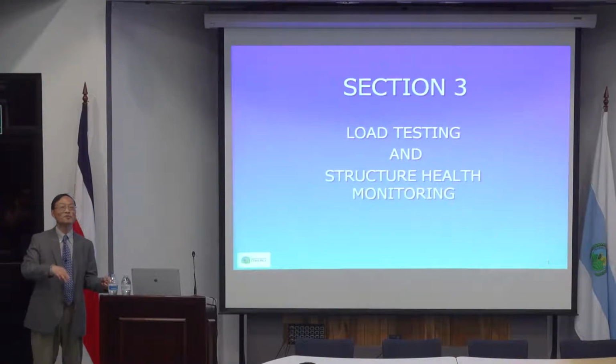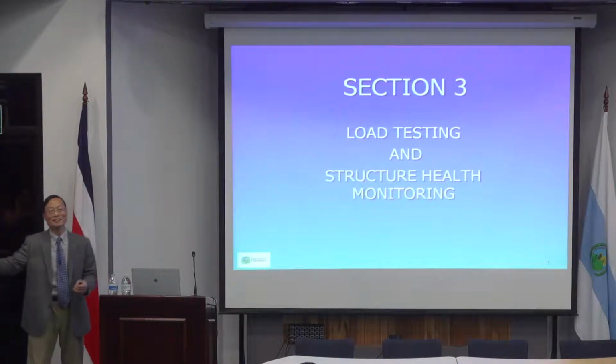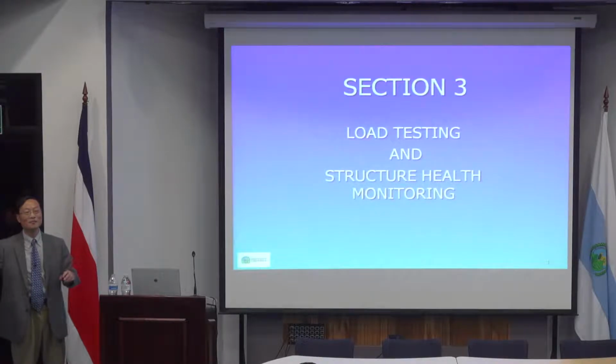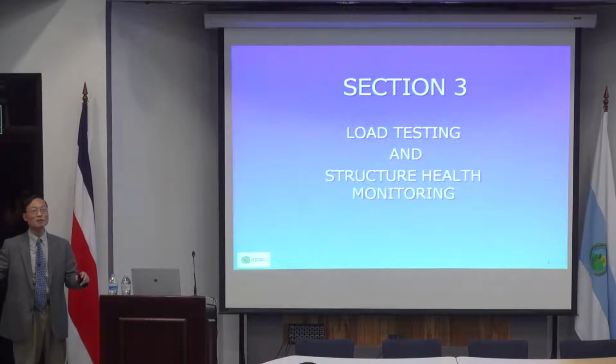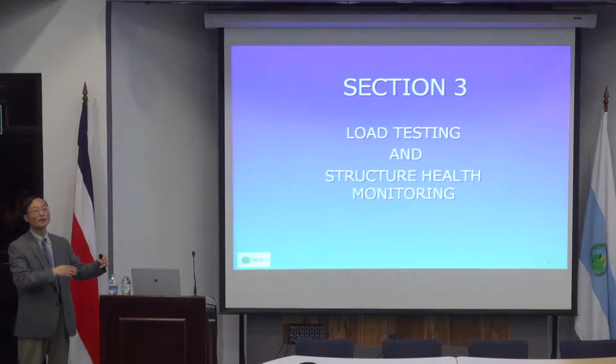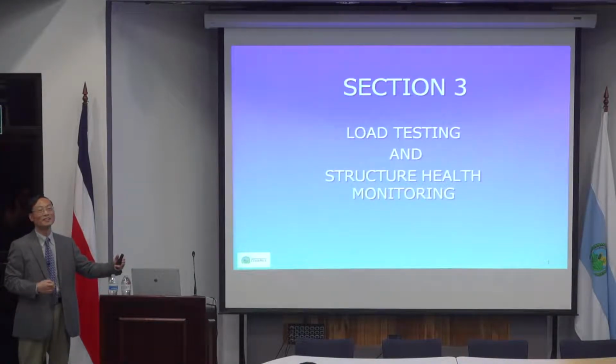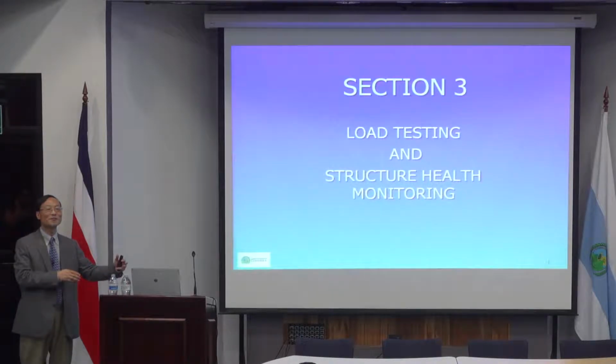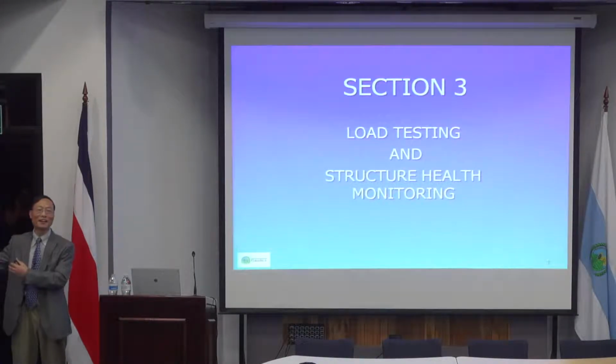When you do the finite element analysis calculation, you will see how much deflection of each girder, and then you just compare it with your testing, and see the discrepancies; usually they don't match. So what you do is you manipulate the transverse member stiffness. Once you modify this transverse member stiffness, then you will be able to match your finite element deflection and stress and your actual testing.